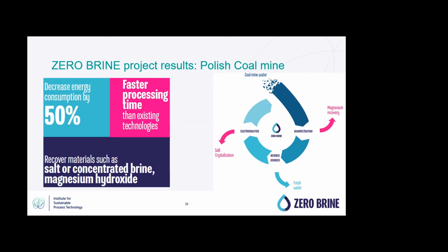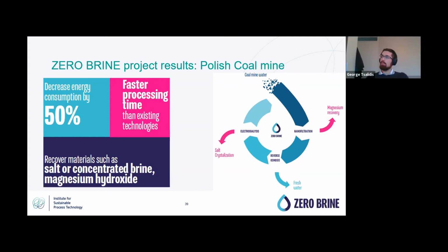So they were condensing the brine, removing some clean water, some distillate, which is disposed to the river close by, and the second one was crystallization, where they were initially removing some gypsum and some lye, and the gypsum was also used internally by the coal mine for safety purposes.